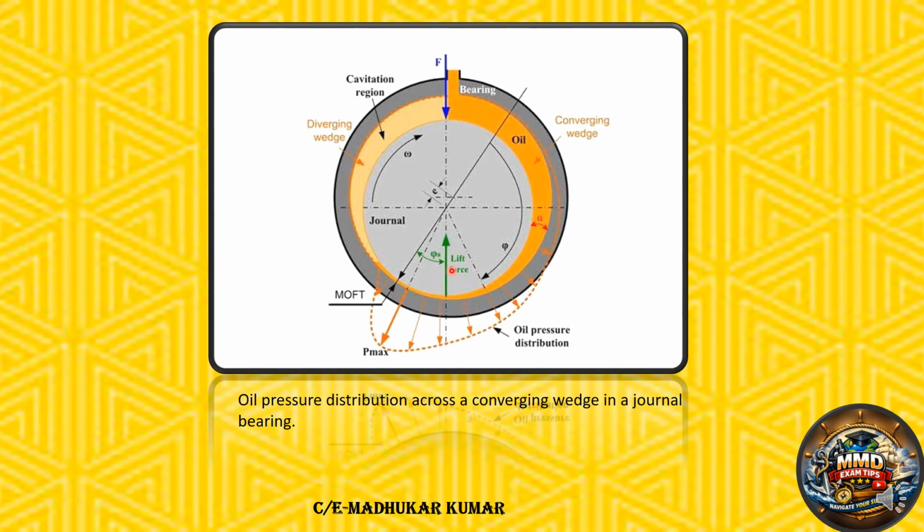Due to the lift force, the shaft will be separated from the bearing, and this distance is called MOFT. We will see this part also. So this is a clear understanding and explanation of hydrodynamic lubrication, wedge formation, the diverging wedge, and the converging wedge in this case.